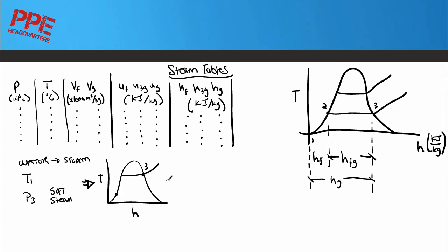Okay, so what do they want to know? They want to know what heat is required to do that. So this will be our state 1, this will be our state 2 up here. How much heat is required to do this operation? Convert this water to steam, saturated steam. So basically they're asking how much heat? They're asking H3 minus H1. And they'll also ask, often, as a kind of a little trick or a confusion, what is T3? Meaning, what is the temperature at that saturated state?